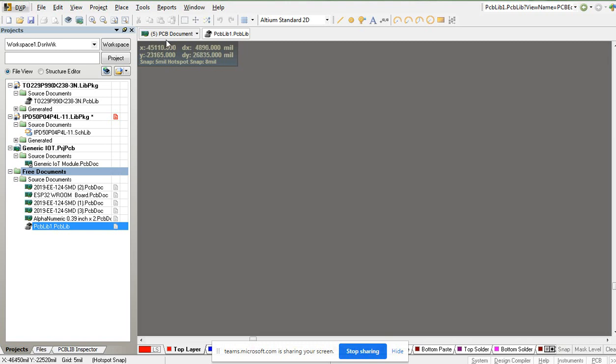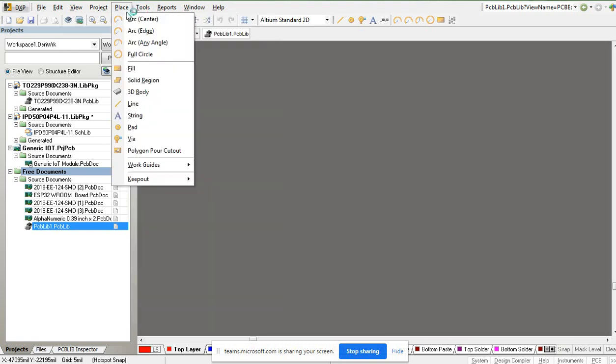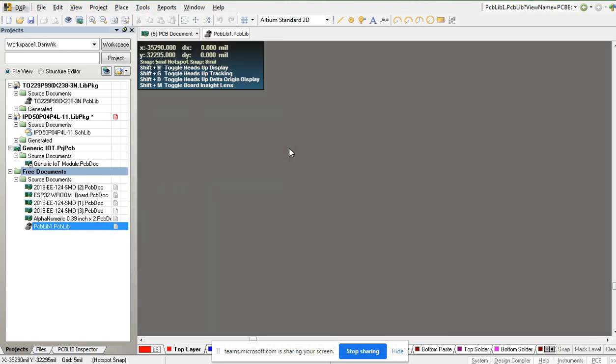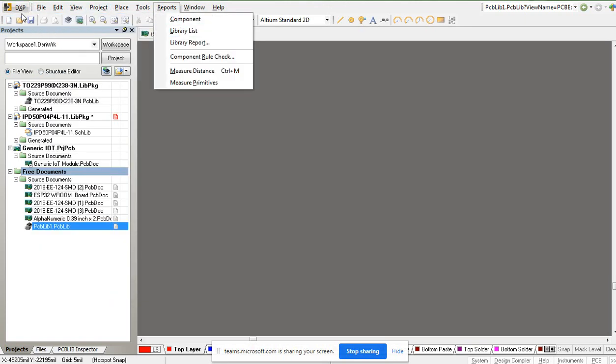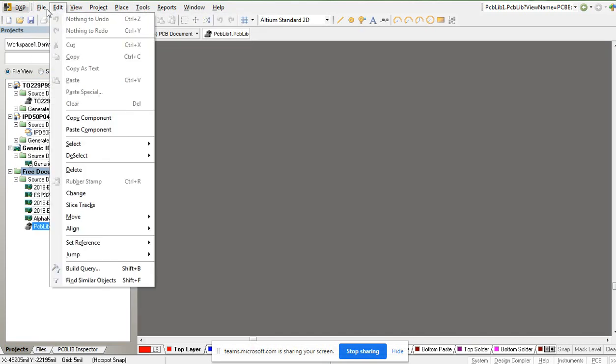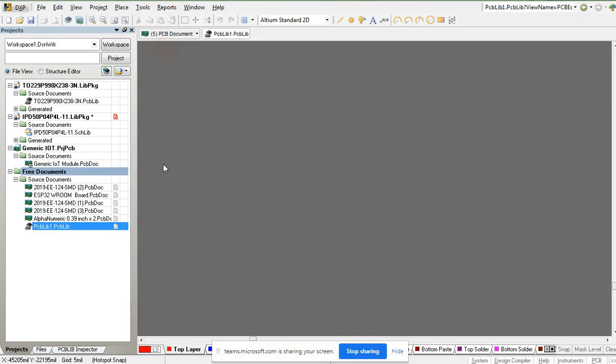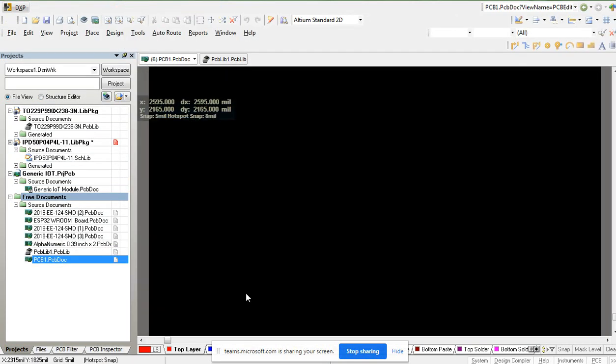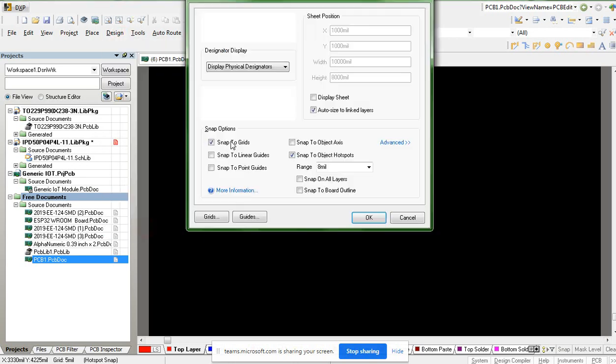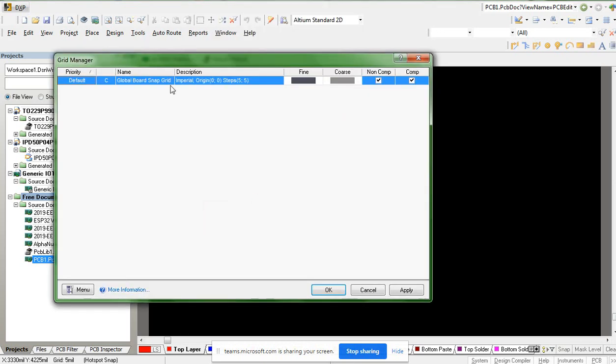The problem personally I feel is that in this PCB library, all the dimensions have to be done in mils. So what I do normally, you can do this also, is first make a small new PCB file. Why I'm doing this, I will tell you. Just make a new PCB file, change the design units to metric, and change the grid lines.